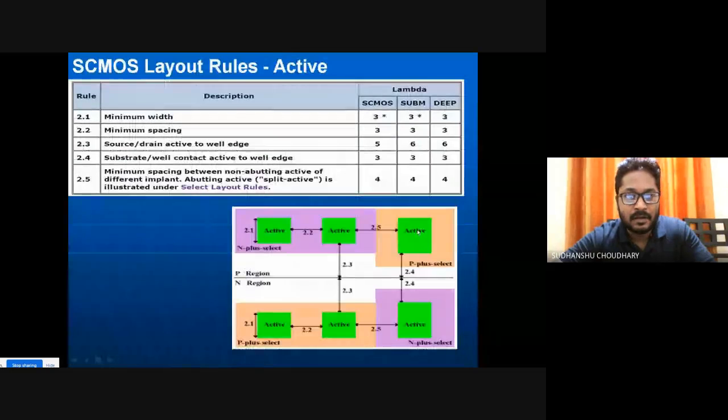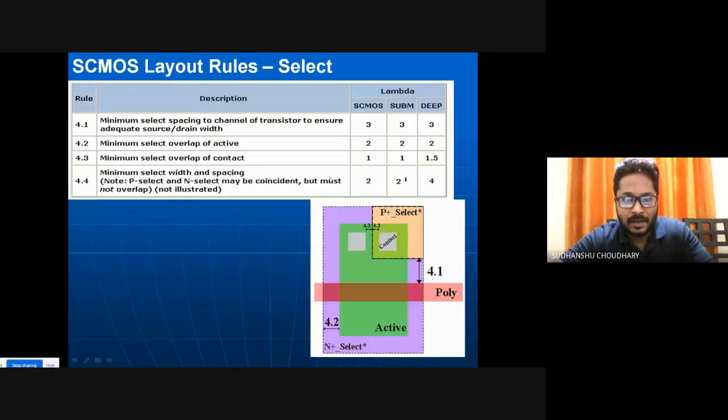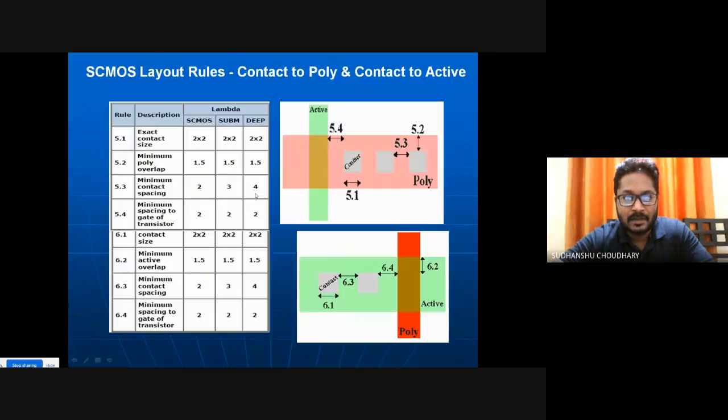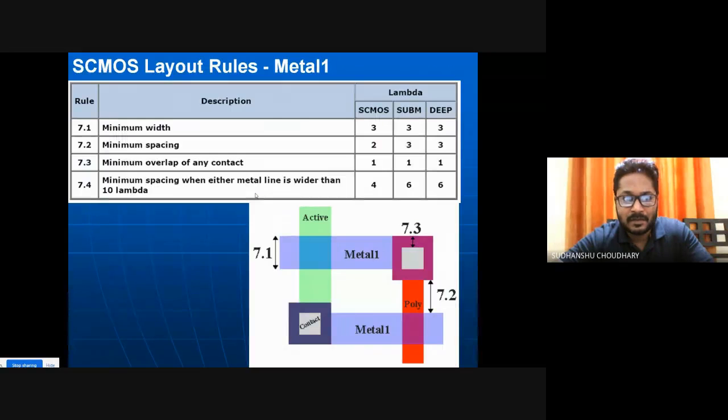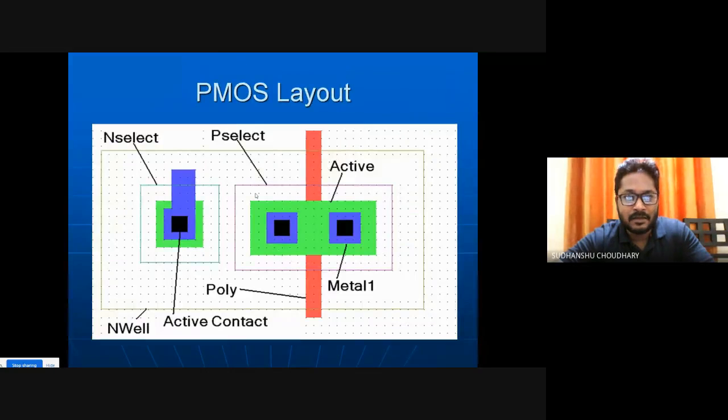So in the last lecture, we had seen the layout design rules, and we understood that these design rules specify the minimum dimensions for each layer that you draw in the layout. For example, we had minimum design rules for poly lines, contacts, via contacts, the diffusion regions, the spacing between two regions or two lines, then surround rules, right? And then we also saw how to draw the layout of NMOS and PMOS, right?